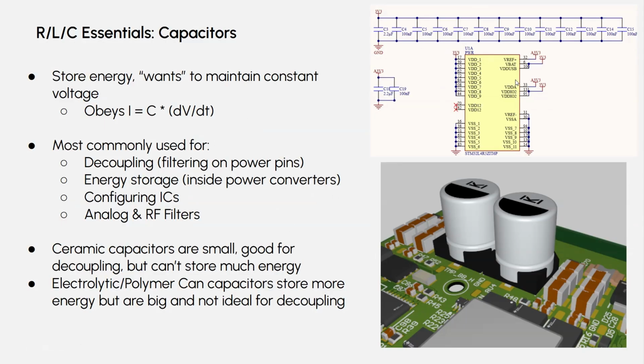So yeah, the concept of decoupling is basically when you have a PCB, you have a lot of different components on there that are pulling power at different times for different reasons. You have, let's just say, USB as your input power supply from your laptop. Any sort of noise or glitches or just any non-idealities in the power supply, which is always going to be the case. Power supplies generally suck, especially ones you haven't designed yourself. External power, like USB power, is terrible.